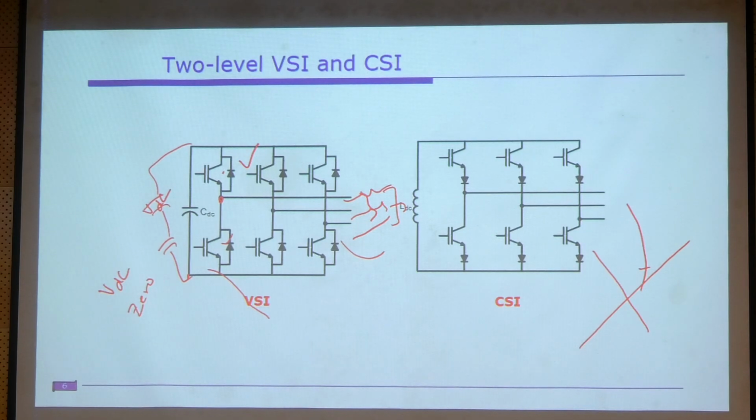Even though they follow the same manufacturing process, the threshold voltages will differ. Same manufacturing process, everything is the same, but due to the material properties, there will be some deviation in the threshold voltages. So that's why in industry they make sure that the threshold voltage difference is just 0.5 volts, when they create the bunches. So one bunch is somewhere ranging from 2.5 volts to 3 volts. They will bunch it, and they will use those devices for the parallel operation. Understood?